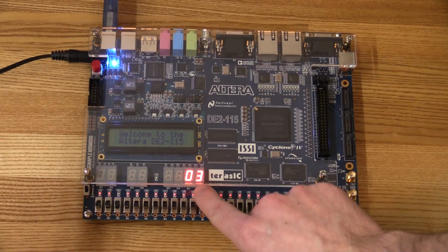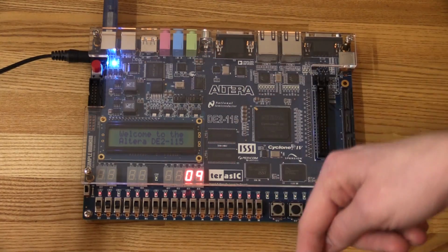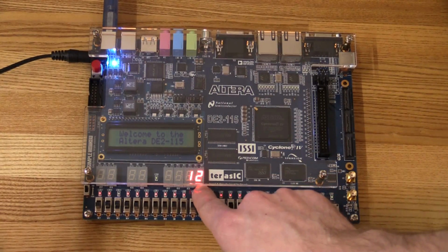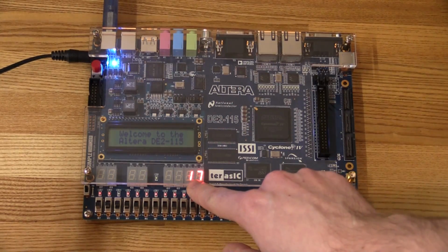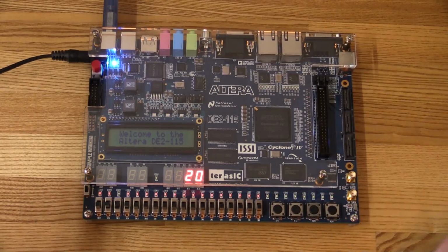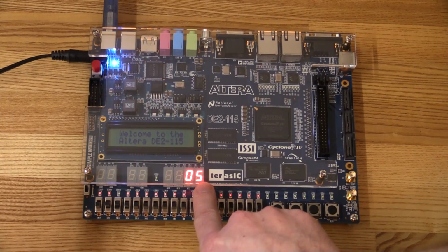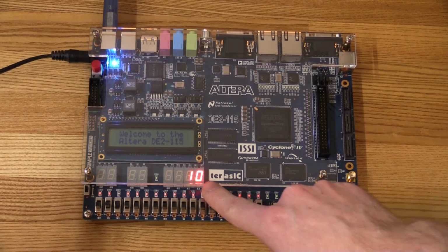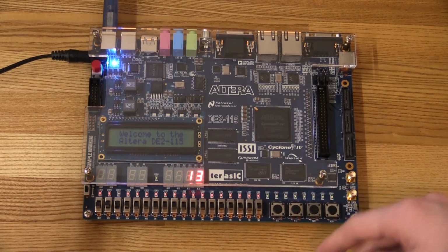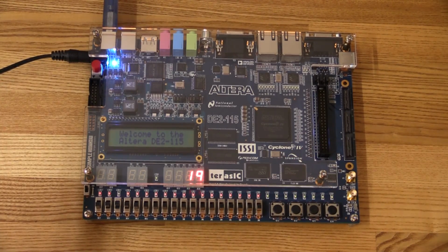So to test if we get an E here, I'll just go ahead and introduce an error. I'll make the first counter count to 10, so that it will try to write 10 in the first display before it counts to 1 on the next one. So there'll be 11 seconds from 0 to 10. And here we go. We are trying to count to 10 on the first display this time. And you can see we get the E. So that's working. Now I'll put it back so it actually counts the correct amount of seconds.